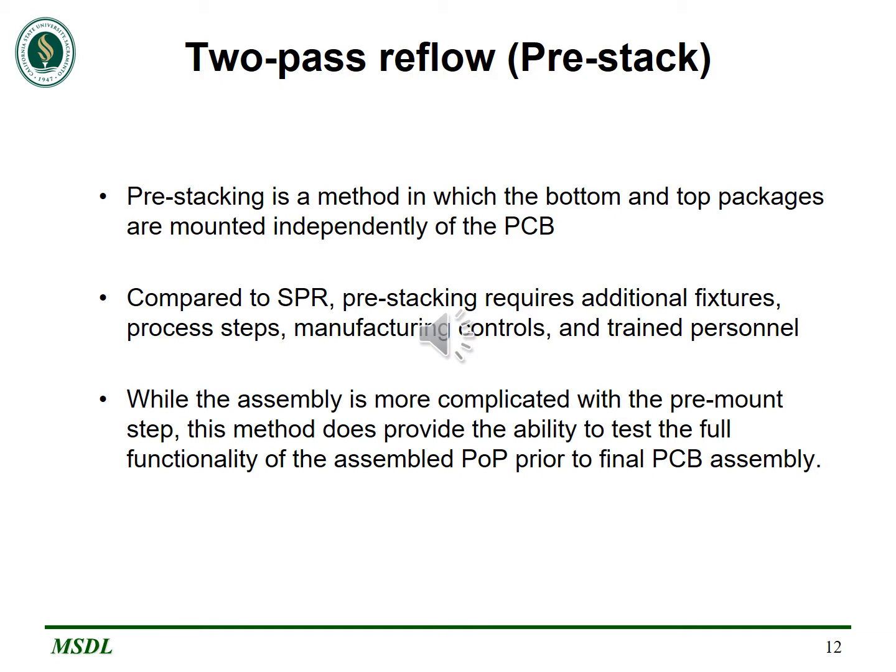The second method is the two-pass reflow method. This method is also known as the pre-stacking method. In this method, both bottom and top packages are mounted independently of the PCB board. That is, first the top package will be connected to the bottom package and then the whole assembled package will be connected to the PCB board.